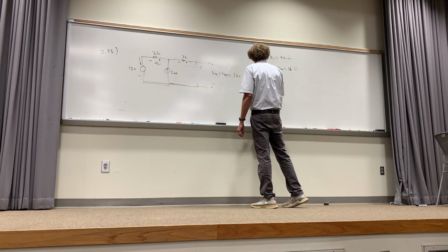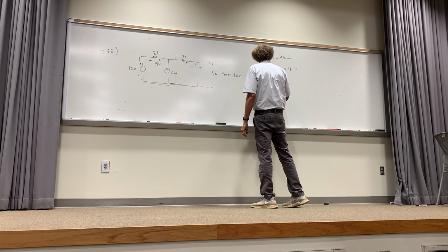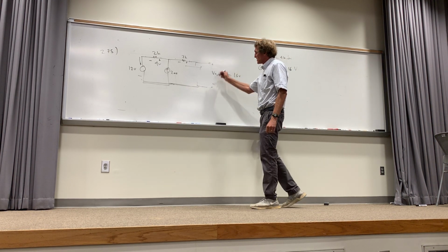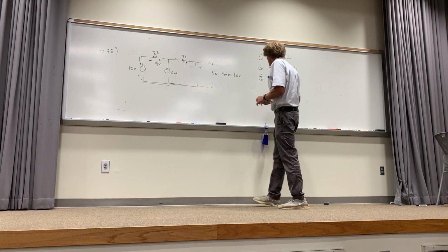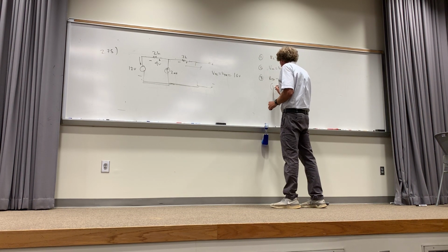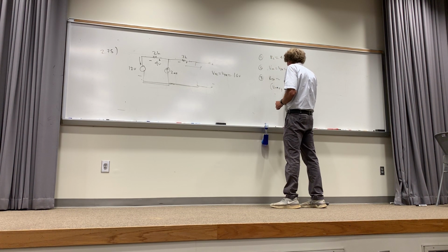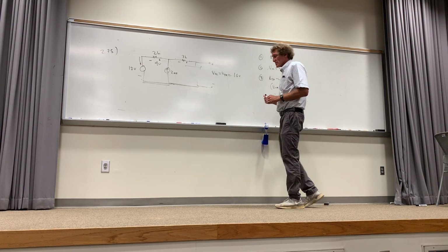Now, the third thing I need is to find R Thevenin, or the resistance between these terminals. And what did I say you do here? You turn off sources. So V goes to 0, or short. I sources go to infinite ohms, right? Or open circuits. Correct, class?